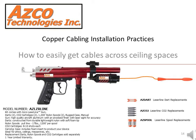Another great tool for getting cables in place is the Azco laser line. This air gun allows you to use a laser, point at your target, and shoot a dart up to 120 feet away. The dart carries a pull line, allowing you to pull the cable back into place to where you need it.